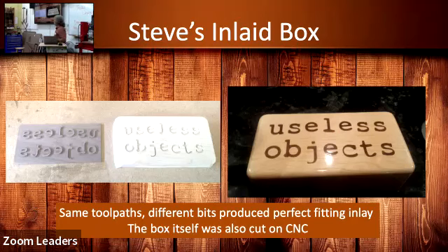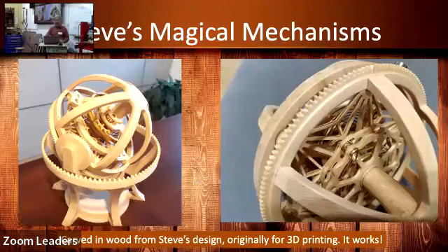The sides of the socket and the sides of the inlay are not vertical. They're typically 60 degrees, sometimes 90 degrees, but 60 is good enough. And that creates a wedge-shaped thing that fits into a wedge-shaped thing. Right. So Dave made the point to cut with V-bits so that you get that around the edges, so that you get the socket to put the inlay in.